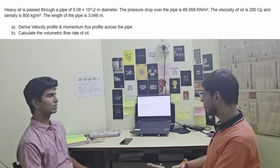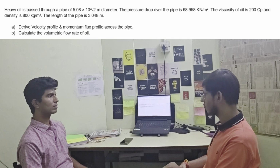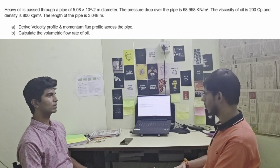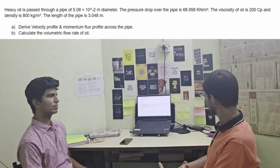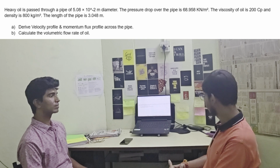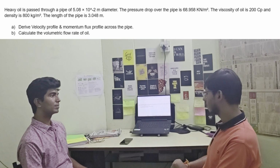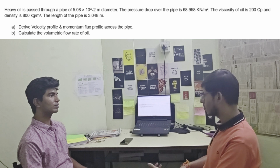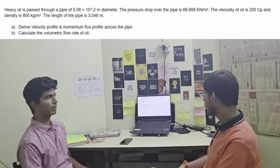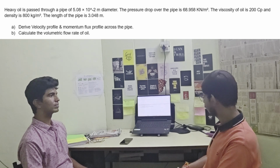And then using Newton's law of viscosity, you can substitute tau is equal to minus mu dV/dx, and then you can get your velocity profile after another integration and using one more boundary condition. So generally we either use one velocity and one flux boundary condition, or two velocity boundary conditions. So the question can be done using that. In case of your second part, which is volumetric flow rate, first after getting the velocity, you need to calculate average velocity, and through average velocity you can easily get the volumetric flow rate, because volumetric flow rate is nothing but average velocity into area. So you can easily solve the question using this.